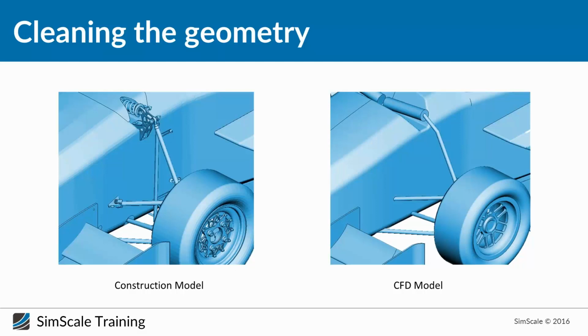Next question is by Venkata, and that's a very good question. How do we debug the problems in any CAD model? Venkata, I would suggest, once you want to get started with SimScale for your own CAD model, first of all, simplify your model. You should not use the same model you use for manufacturing later on.